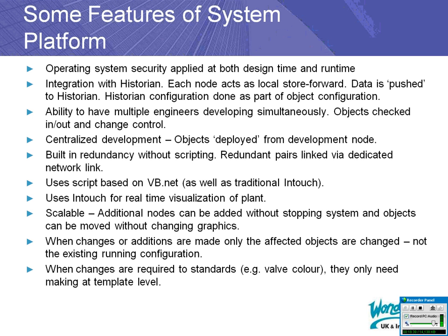When you need to change a standard, for example, a valve colour, then with InTouch, you used to have to go back through every instance to change that colour. That changed a bit when we had the symbols, that they were centralised. With System Platform, if you want to change the scripts that are associated with the valve, or add an extra point for that valve, for example a mid-position, you only need to do that at template level, and that change is then propagated down throughout all the instances used in the application.